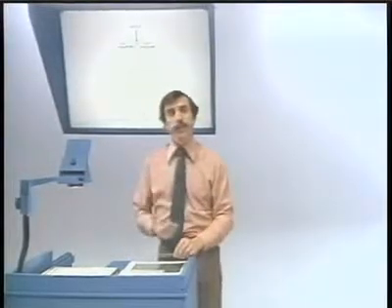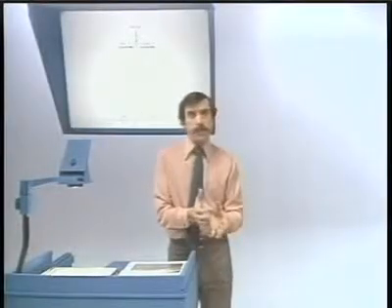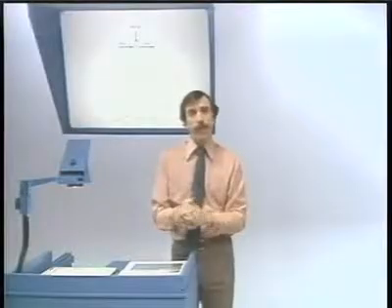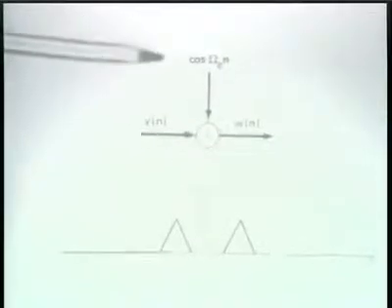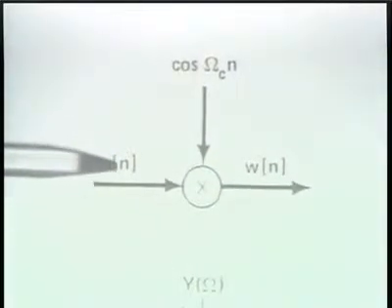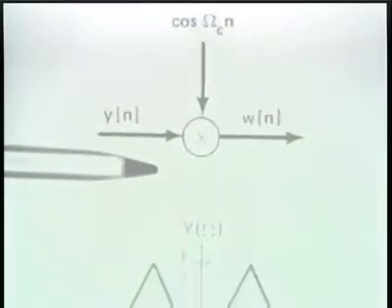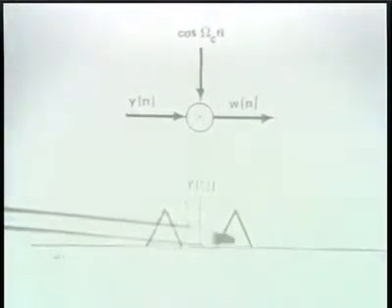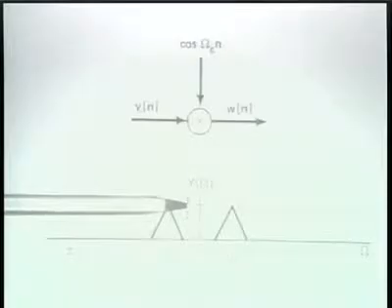In particular, let's consider demodulating by taking the modulated signal and again putting that through a modulator, again with a carrier which is cosine omega sub c n. If we do that, we have a demodulator, or what will turn out to be part of a demodulator, as I indicate here. The spectrum of the input signal is, as I had just developed, a replication of the original spectrum around plus and minus omega sub c with an amplitude of a half.